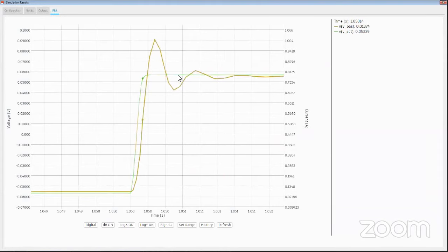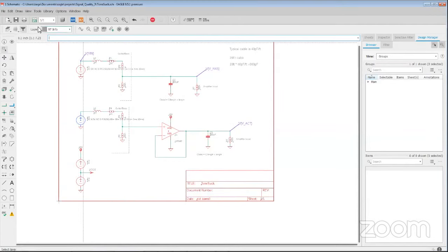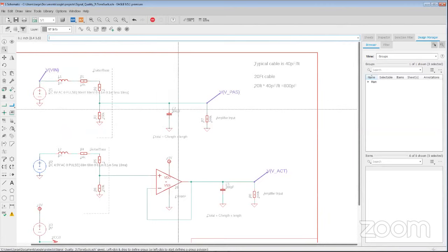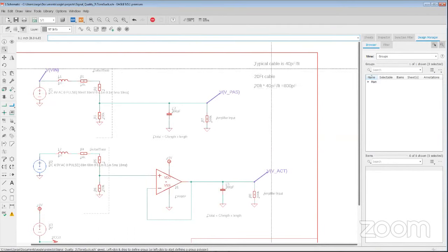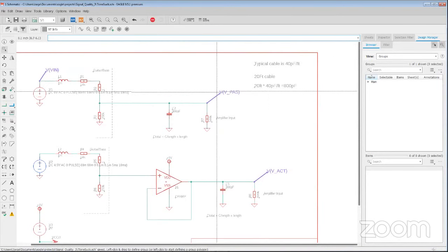So what's the key takeaway here? What are we trying to arrive at? That's why I called this file tone suck. What can happen in many situations is that if you have lots of effects, lots of things before you get to your amplifier, and everything is true bypass, you're basically just adding cable of different qualities, of different capacitances.